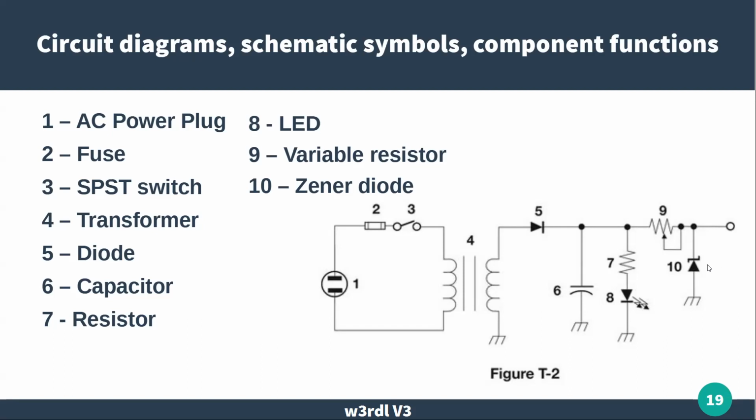which is one of those diodes we didn't talk about, is the Zener diode. And it's slightly different in that it has a much lower reverse breakdown voltage. And they can be manufactured such that it has a specific reverse voltage breakdown.